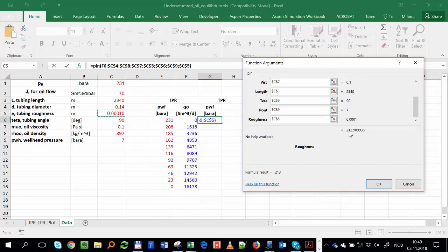Does that make sense? Yes? Why yes? It's not any more gas, okay? It's the density. It's the liquid, okay? And if you see the density, it's almost close to water, okay? So every 10 meters of oil, more or less, that gives you 1 bar.